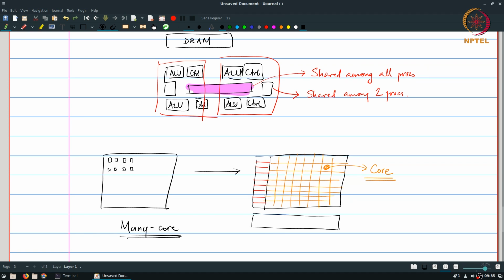The primary difference over here is how are we able to get such a large number of small cores? By stripping away a lot of the control, simplifying the logic, eliminating a lot of the out of order and speculative execution, and saying that each individual core over here is a relatively simple piece of hardware, of course still capable of computing and in fact performing floating point computations, but it just does one job, which is the floating point computation, and does it well. In that way, we can create a large number of cores of relatively small size and fit them onto a single silicon die, have large amounts of distributed cache, so to say,